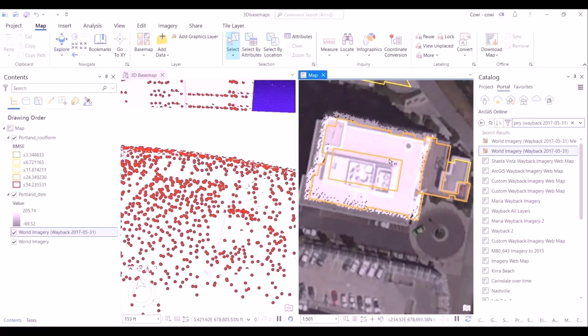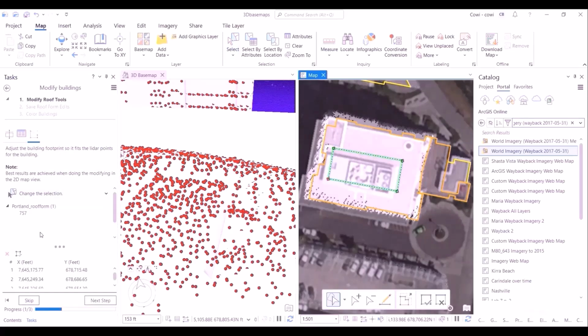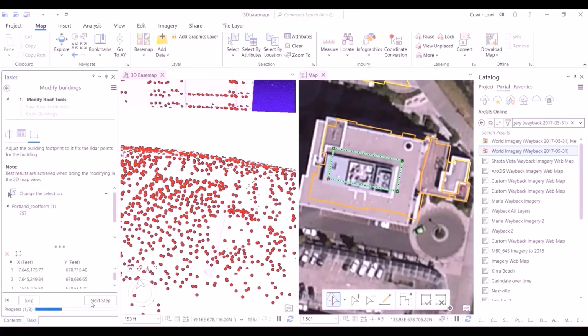What we will do is correct the shape over here, because of the elevation value right at the middle, where there appear to be some sort of exhaust fans. So the shape which was detected was slightly distorted, as in it was away from it. So we use a manual tool to edit the vertices so as to place it directly on top of the particular cross section of the building roof.